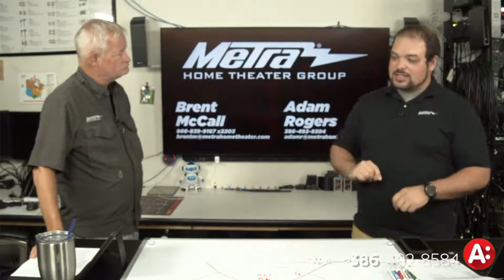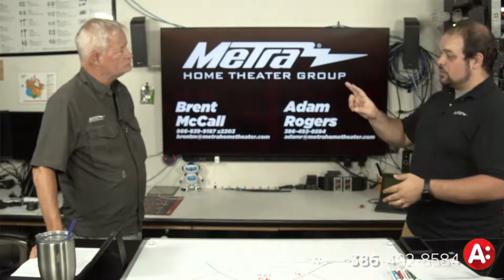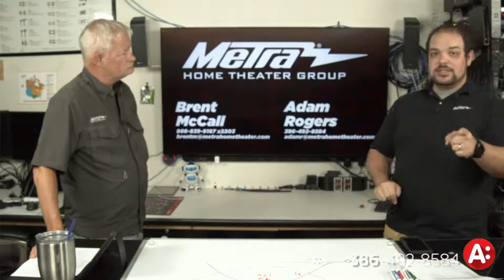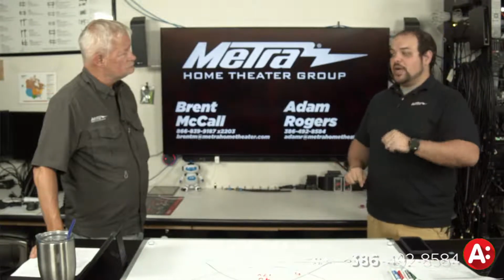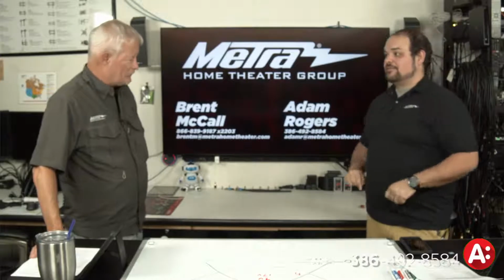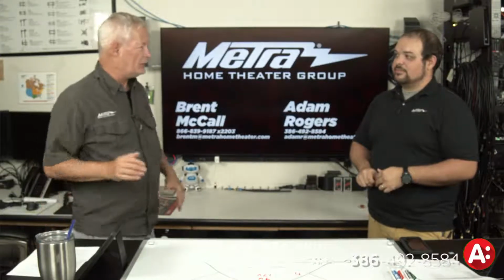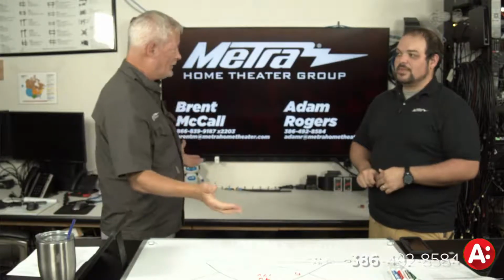Now the way that it does this is kind of interesting. I thought that it was only the blue pair that did the power. I thought it was just a single twisted pair. It's not. The blue pair is your positive. The brown pair is your negative. And since we're not carrying any data, the differential distance doesn't matter. It doesn't matter at all.